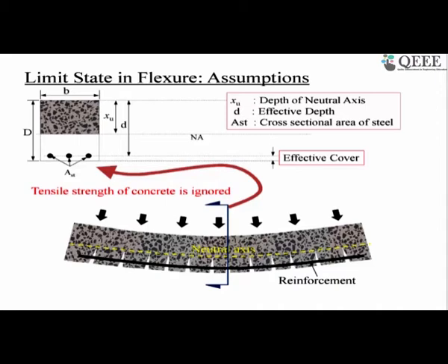For instance, if you are designing an offshore structure, then you need to provide more cover. If you are designing, say, a foundation, you need to give more cover. So how much cover you give depends on many parameters: the structural component you are designing and the environment the structure is subjected to. IS 456 has a detailed discussion on cover for different structural components and for different environmental exposure.